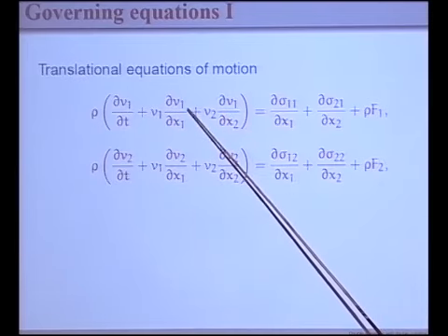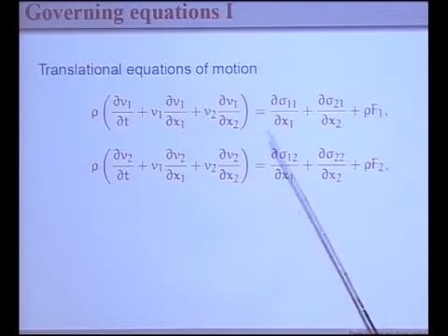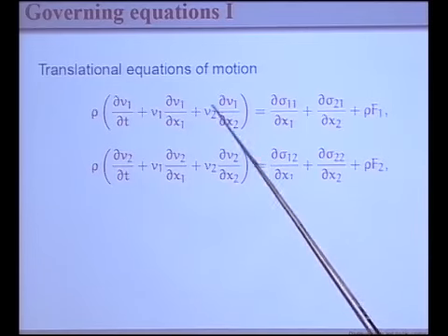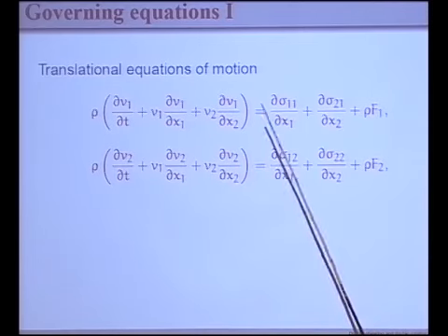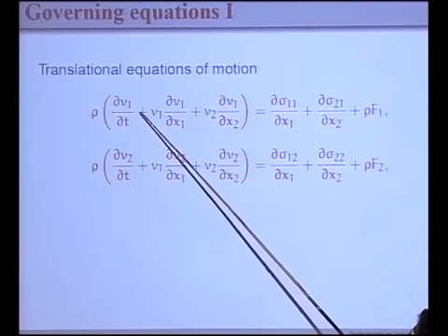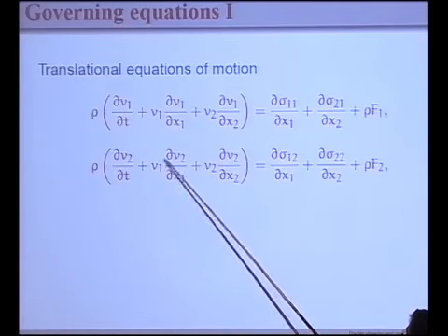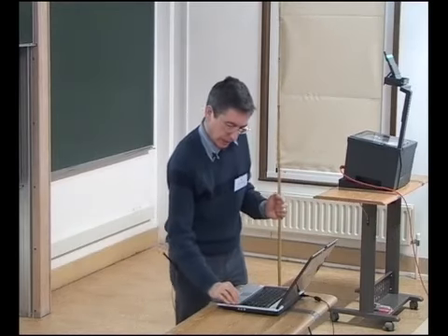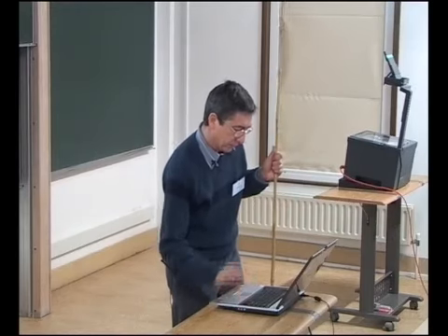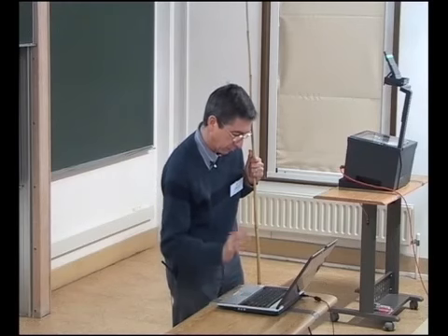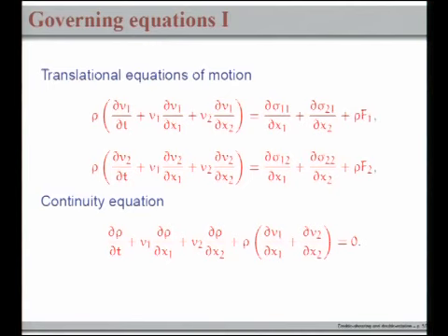The stress tensor in general will be non-symmetric, so I will distinguish between those. For plasticity models, it's usual to neglect the inertia terms, so usually there is a zero on the left-hand side. As I say, I'm hoping to keep a little bit of rate dependence by keeping those inertia terms in. Also, I want to talk about ill-posedness, and that only comes in when we talk of time-dependent systems, so I certainly need to keep that left-hand side through.